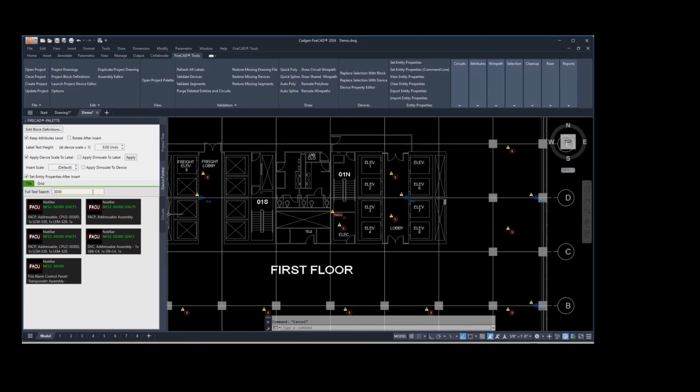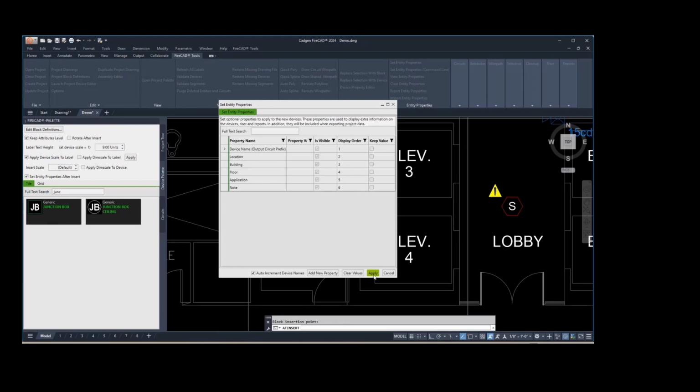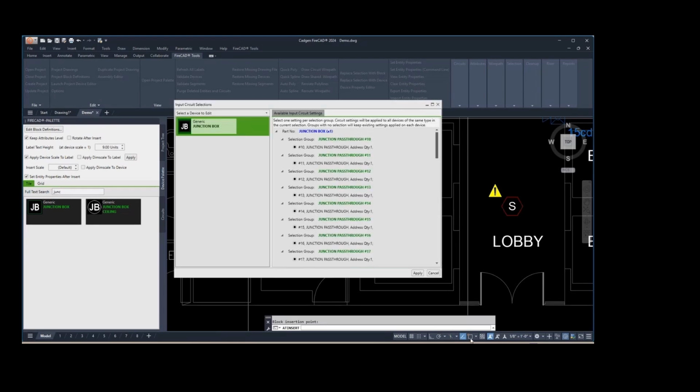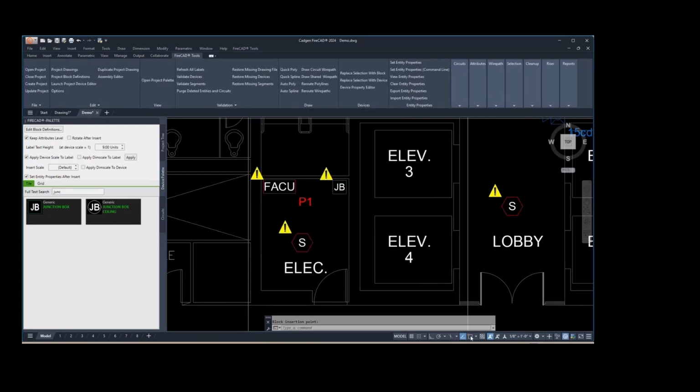Let me get some junction boxes. The reason I'm going to use the junction boxes is that I want to have a really easy way to make a riser. This is a three-story building, and one of the great features of FireCAD is the ability to create riser diagrams automatically. The junction box is helpful in that endeavor. Notice I turned my snap on,